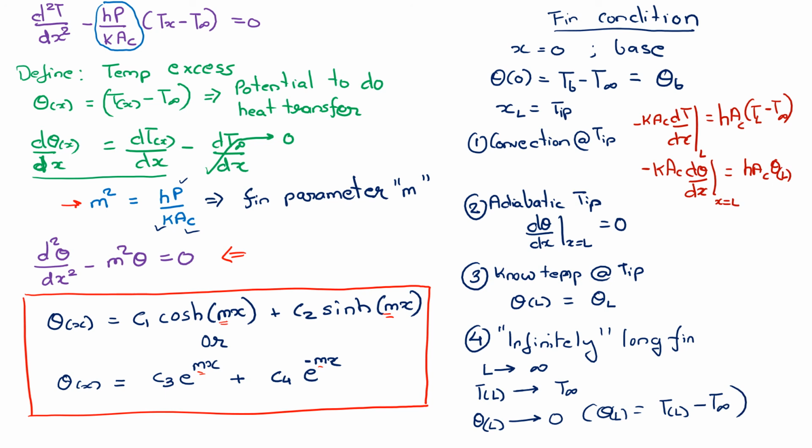So these are the boundary conditions that you must remember. These are very important, and you should be able to identify which boundary condition to use based on how the problem is framed. And the other thing to note is that these are not your trigonometric sines and cosines, but these are hyperbolic cosines and sines. So don't make the mistake of confusing them with regular cosines and sines.